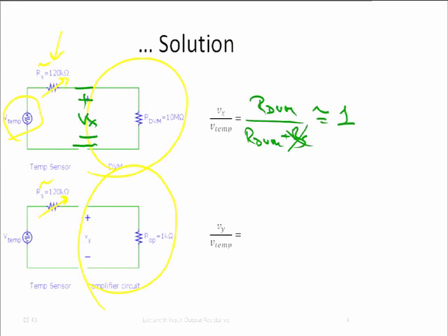Now in the second situation, at the bottom of the slide, we again have such a voltage divider. So we have ROP, that was R1 in the slide before, over RS plus ROP. It turns out that ROP is negligible compared to RS. So this is on the order of 1 over 120, approximately. And it varies a little bit because RS varies a little bit. That's exactly what your colleague said, okay?